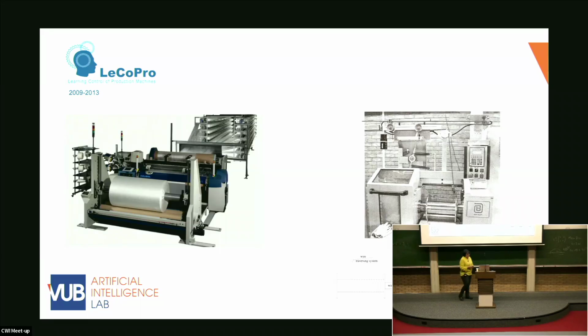So here, how we did it was, two things can happen. So two problems, the one at the left-hand side and the one at the right-hand side. The middle is fine, because then you have a very nice flat surface. And that's very important, because at the end you have to unwind the bobbin if you want to use the material. Therefore, the objective is to have it as flat as possible. So you can have two problems. You can have what they call a hill or a valley. And how can you detect that?